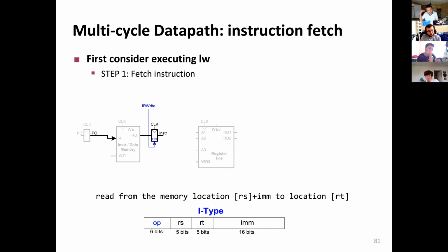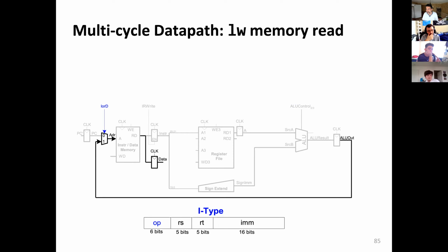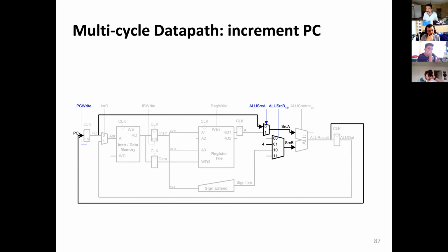Even though they are the same, since this register file has been defined in the ISA, if we write to it in a cycle while the instruction is still ongoing, it's not finished. It's not finished by any means, like we have other states, right? It will be finished when we are done at the end, right? But in the middle, it's not finished. So if we write things in the middle, we will violate this property and things could go wrong.